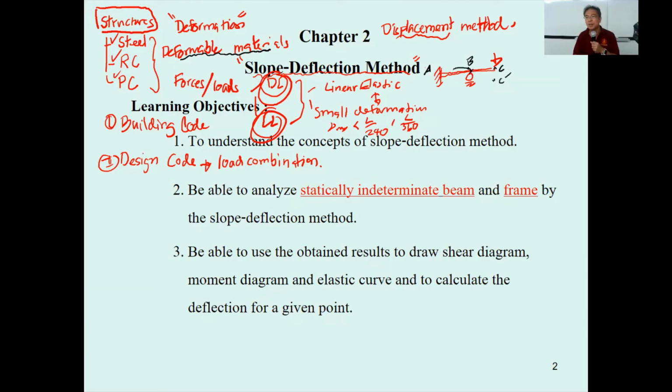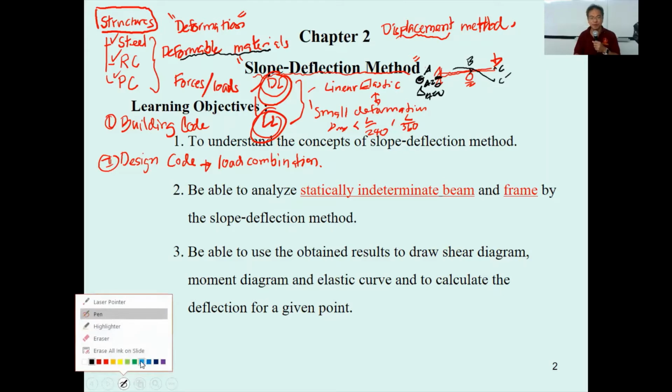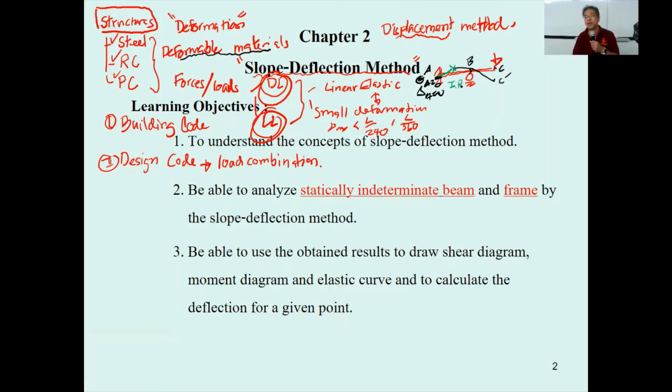So this one is supposed to be the shape of the structure, and it's going to be concave downward. Since this one is fixed, theta sub A is 0, and delta sub A is also 0. So over here, the curve must change shape to concave upward. And then you get this one as the inflection point. And what you have over here is called the displacement. This is going to be the delta sub C.